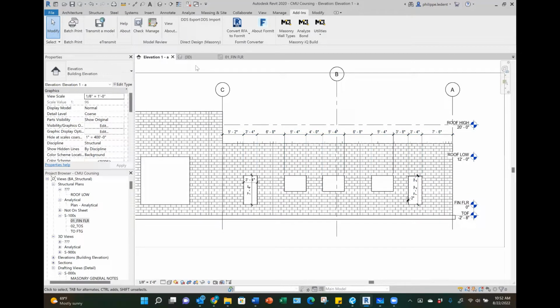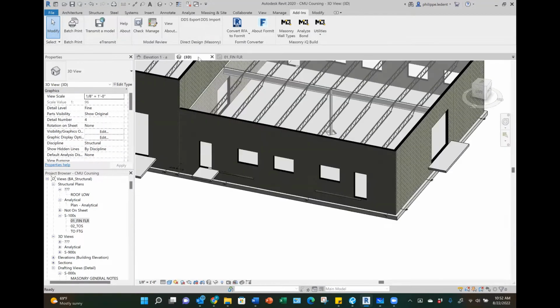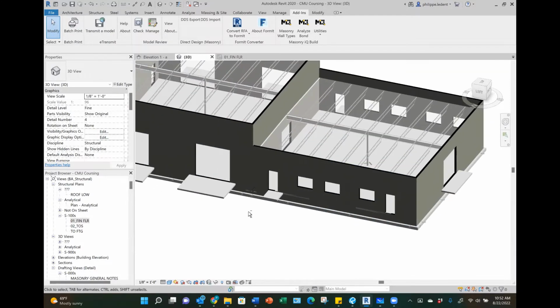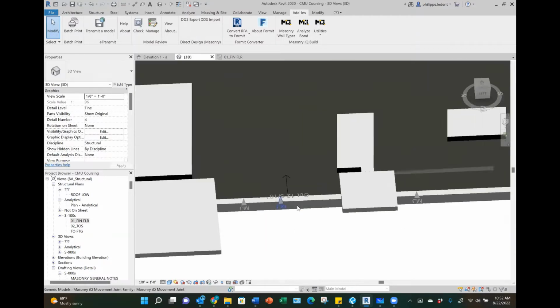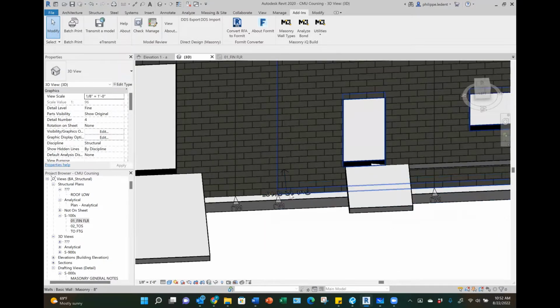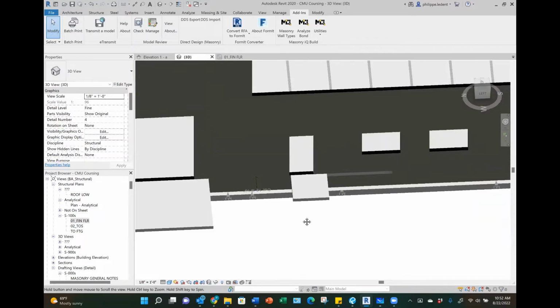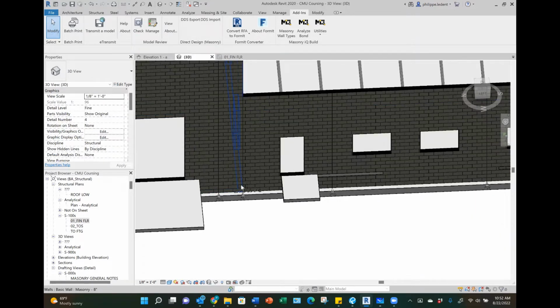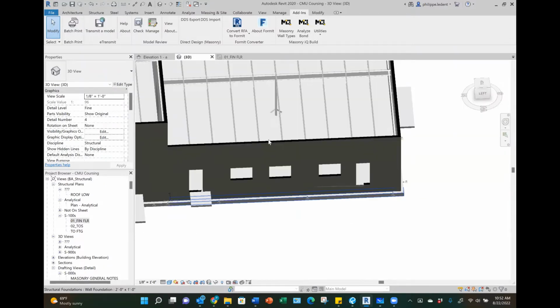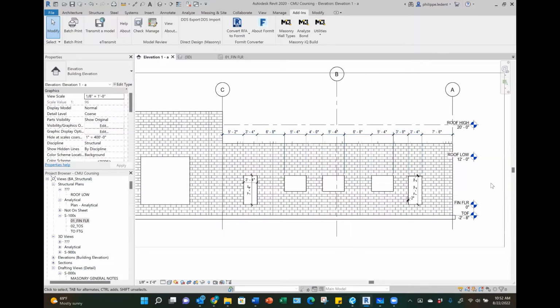And the nice thing with using Masonry IQ is it's going to tell us where we have an issue in terms of cuts. If you look over here and we zoom in, it's telling me that we have to cut this unit 12 and 3/16 of an inch. That means that up this wall elevation, we are going to have to cut all those units to allow our overall dimension to equal what I had laid out, which obviously we don't want to do. That's going to affect productivity and cost.